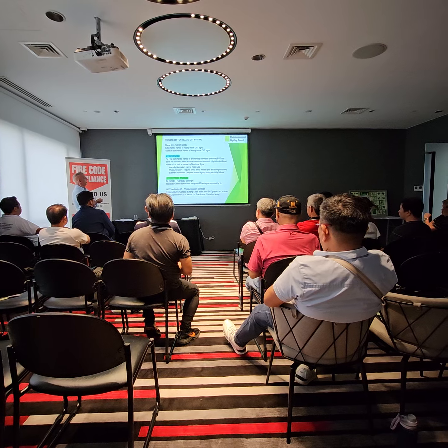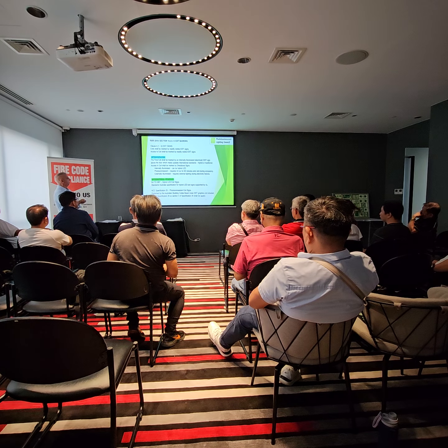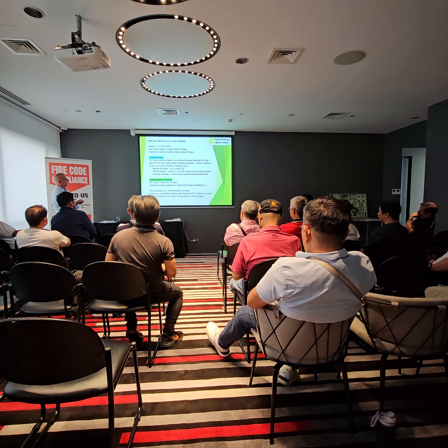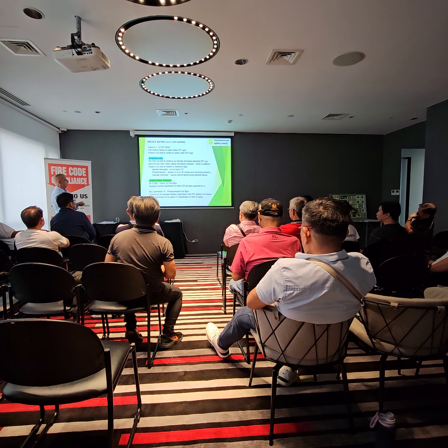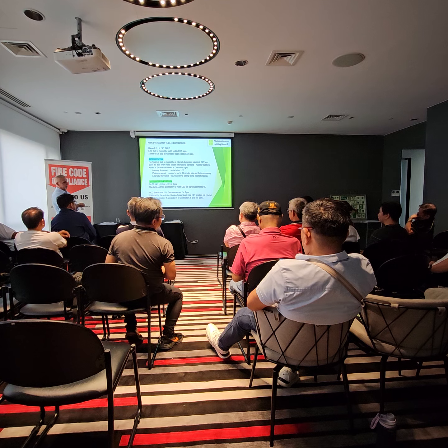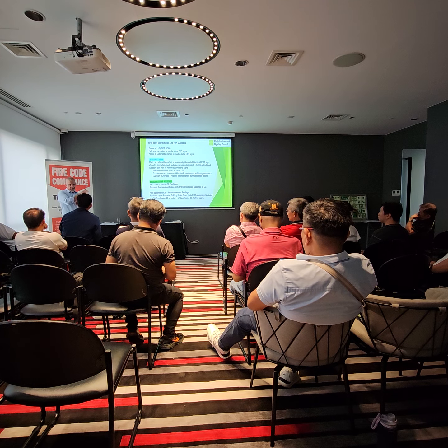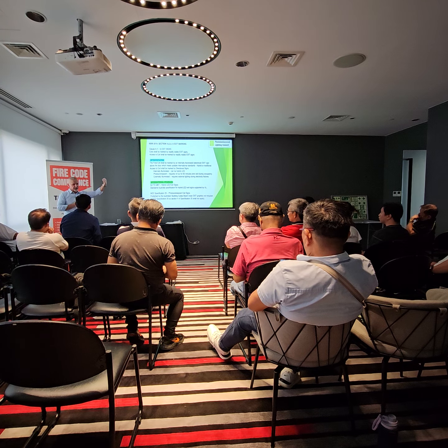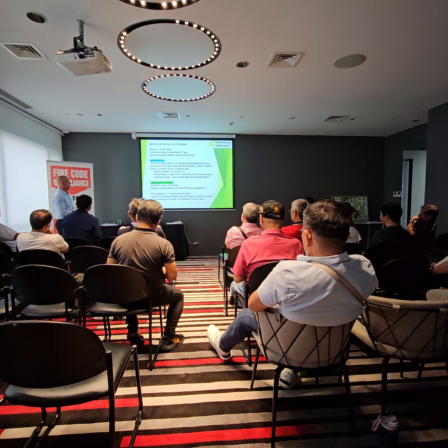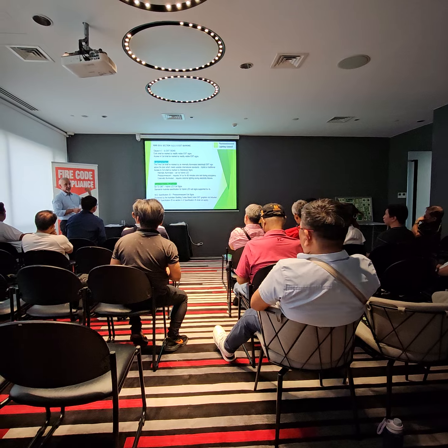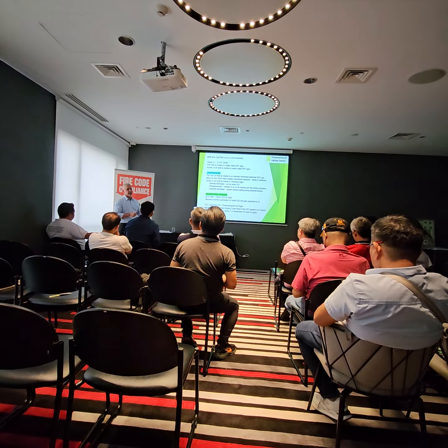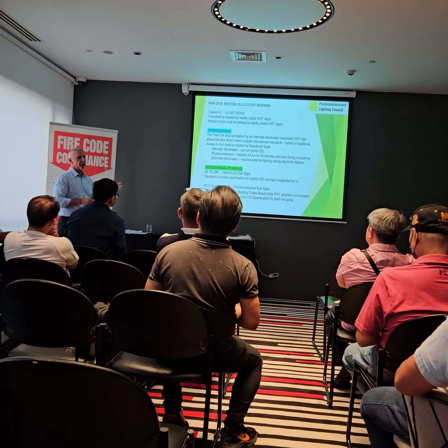Then we've said, okay, there's that standard for the hybrid LED sign, and if it's a passive sign, that's the standard for a passive sign. And when I say passive, that means it doesn't have its own light source. So it's just sitting there, so it needs that 54 lux on the face of the sign for 60 minutes before a building is occupied.